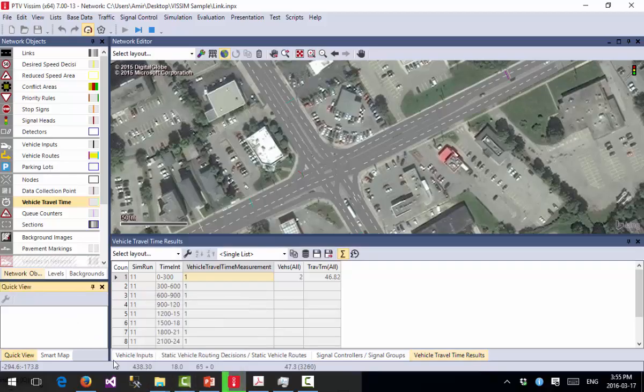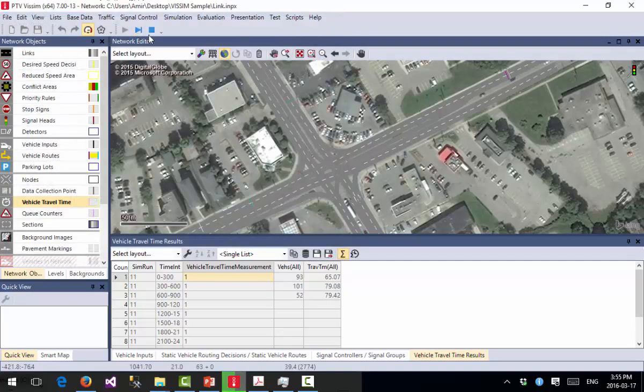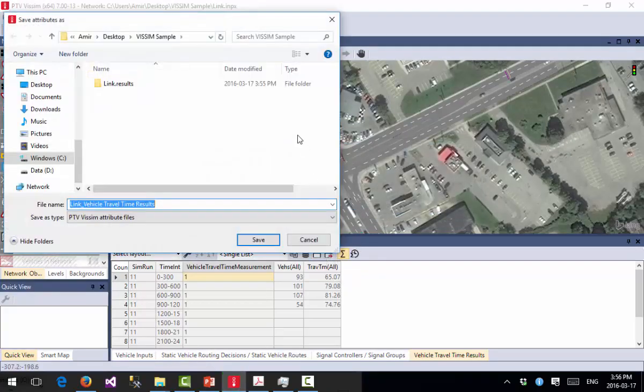As you can see, the speed increased a lot because it's not going to update the interface for me. Here is the simulation seconds. As you can see, it doesn't update here. If I remove this one, now you will see the vehicles and the values being updated. But let's do it for the rest of the simulation, and I will export this one. So I can say save this directly to a file, and it will ask me where I want to save. Let me stop the simulation, and I can save it to a file. Okay, link travel time results, for example, test 1.